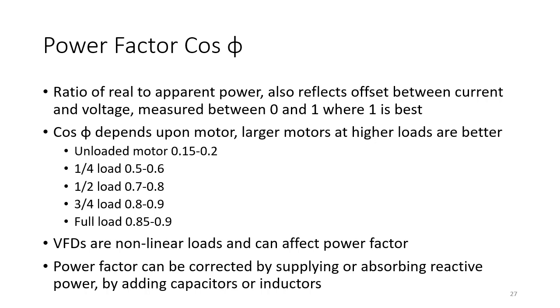So power factor, it's important because what it means is you're effectively wasting power. And it's also a problem for the generator companies, because they want to supply power factor at a ratio of 1 where the current combines with the voltage, because that's what they need for their generating equipment, and it's also what you need for the distribution equipment. Otherwise, if you have lower than 1, you can cause heating in the power transmission wires, and that leads to extra losses, and it costs money and can cause failures. So the power generators want as close to 1 as possible, but in practice you can't necessarily achieve that.